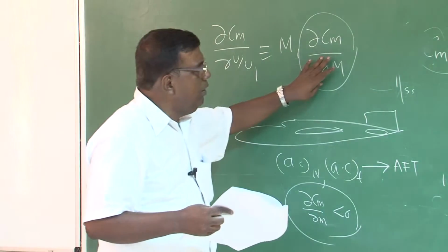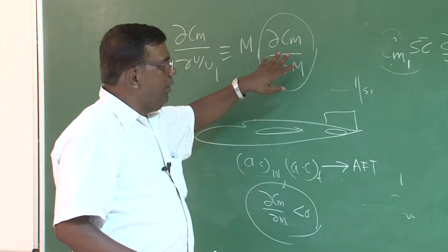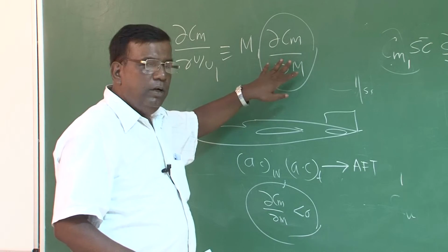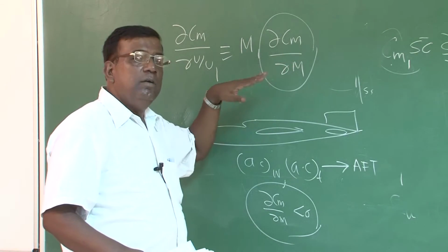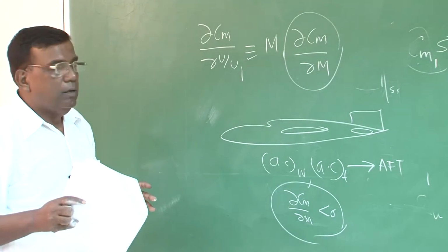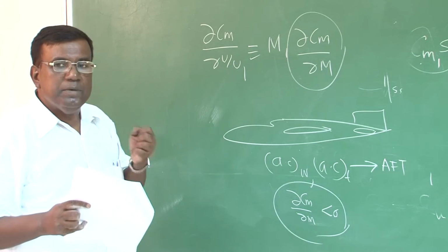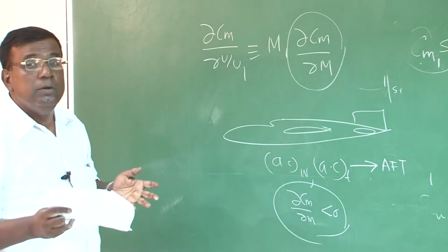But all of this you can estimate approximately through analytical methods, fairly accurately through wind tunnel testing, and reasonably well through flight testing, or all together in a corroborative manner in an excellent way. All the derivatives can be captured within 10 to 15% depending upon what regime you are operating.